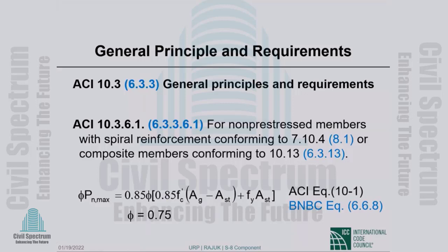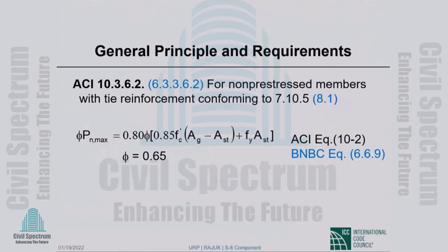You add the two together, you have the column axial load, and we multiply that by a phi for reasons that I explained on the first day. And then there is an additional 0.85 that we will discuss in a second. If it is a tight column instead of a spirally reinforced column, then that number of 0.85 changes to 0.8.